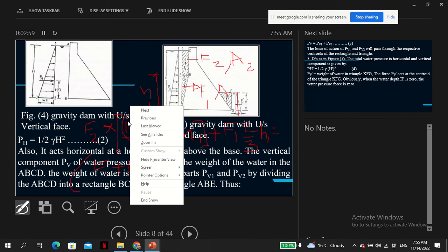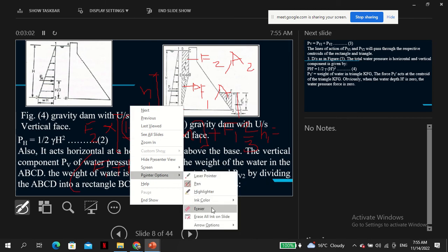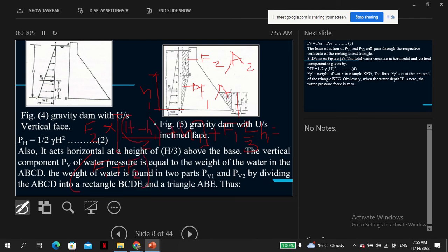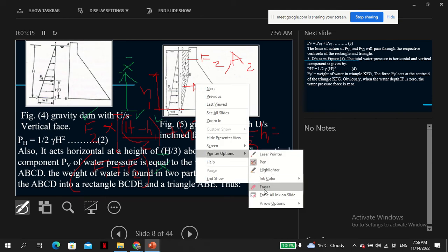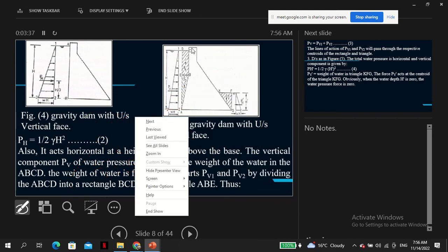times, so you don't know where the centroid is. I'm sure you have done this even in mechanics. So say the centroid is somewhere we don't know, x bar, somewhere there which we don't know. So this is the same as x bar, which you can solve because all this you should know. H1, all this you know. So that's how to find the overall centroid of the force, where F1 and F2 act at the effective center of gravity of this mass.